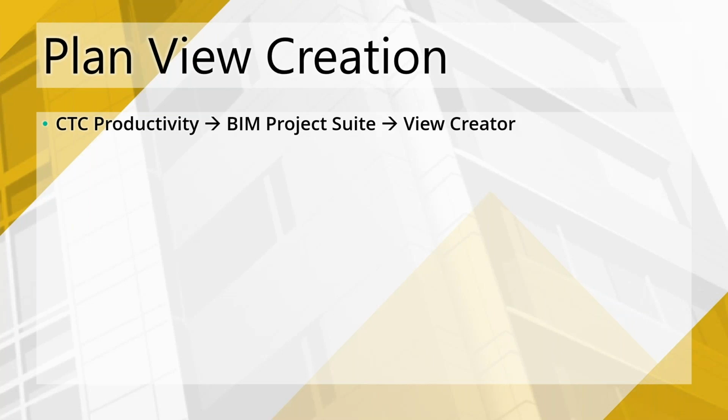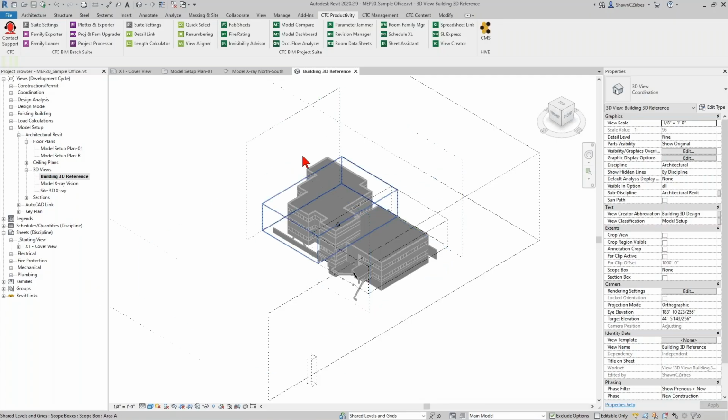Now, if you don't like any of our view names in the MEP productivity pack, you could certainly be more aggressive and delete all of the floor plans out of the model, 100%. I've left a number of level 1 floor plans and roof plans that are already there. But again, if you don't like those view name conventions, delete them all and just use the view creator to create your own view names, named exactly how you want them named, okay? So let's go into Revit here and actually do this ourselves.